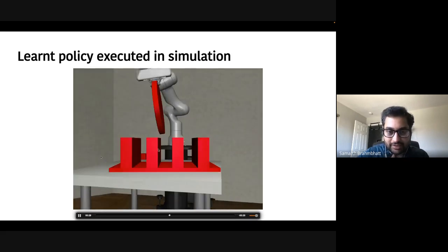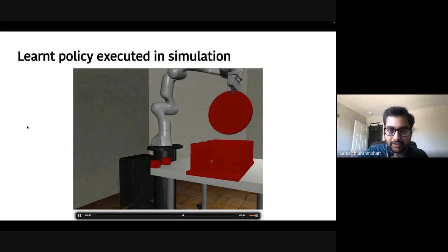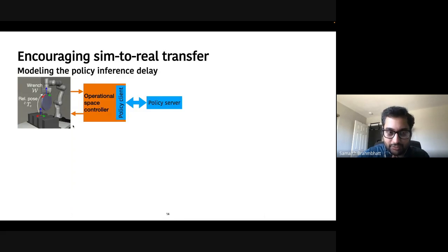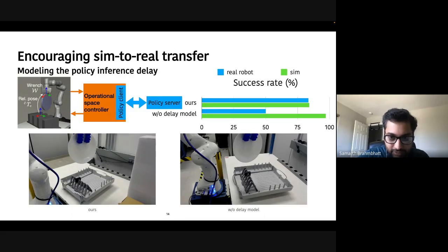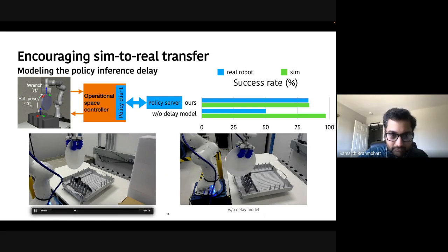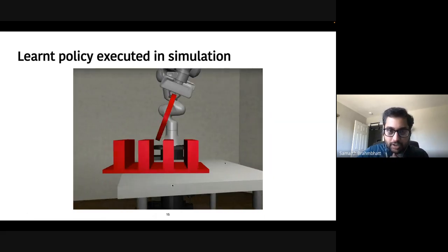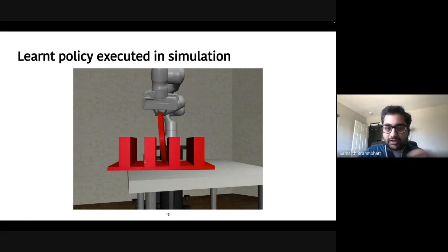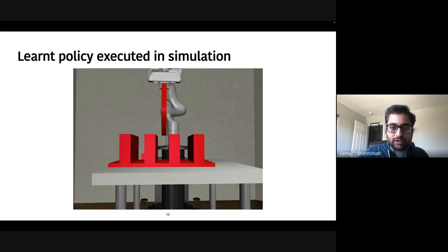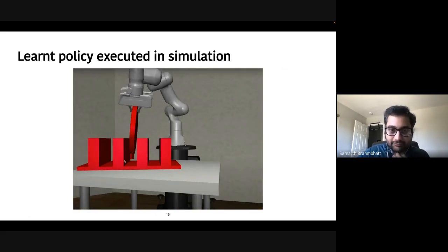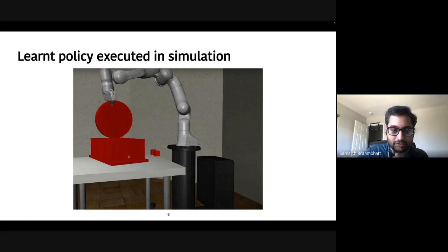We just have these rectangular slots, a very simple ideal cylindrical plate, and the gripper is modeled as a rigid gripper. But if you see some of our execution videos, it's actually a soft gripper, which adds a little bit of damping to the forces and torques. We did some work in modeling the gripper as well, but we found that it wasn't necessary for this task. I think for more complicated tasks, we might need a model of the gripper that is also flexible.